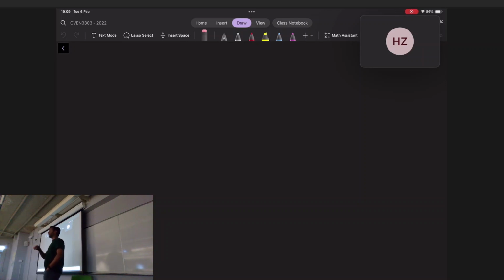If you have any questions on load combinations, we can go through it after. The second thing is tension design. Within tension design, there are 2 parts: yielding on the gross section and fracture on the net section. That's literally all it is. With that amount of information, you have enough to be able to do the first set of workshop problems. Hopefully when the lecturer talks about it, you're across what he's talking about. So conceptually, for the rest of the course,